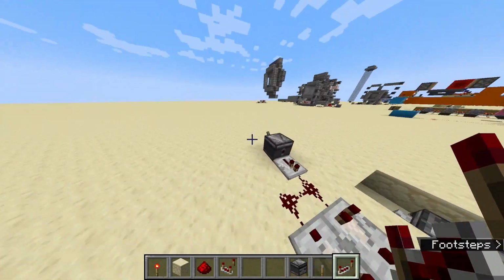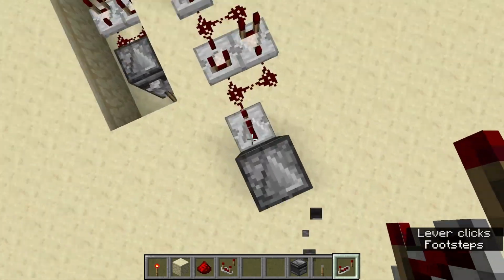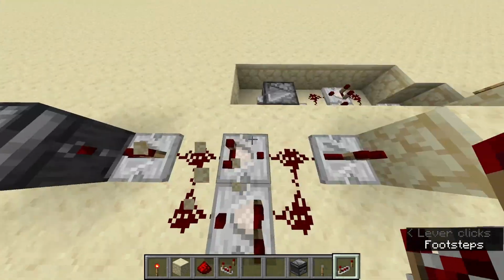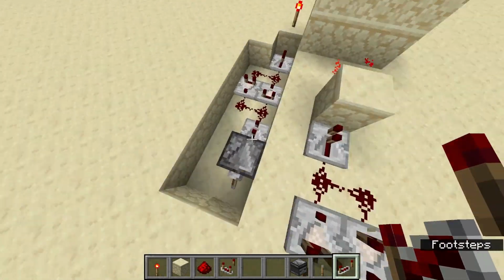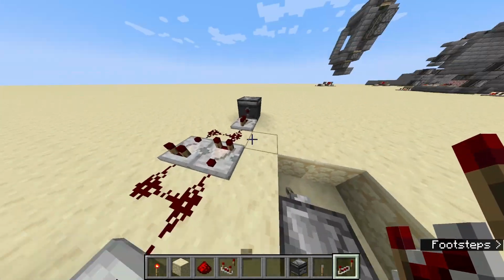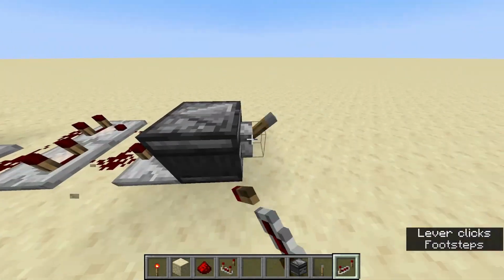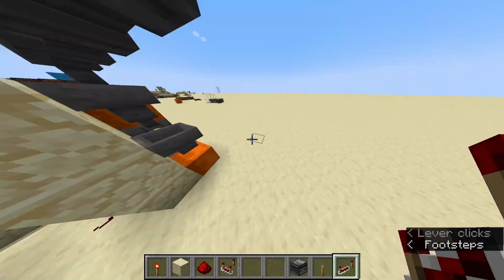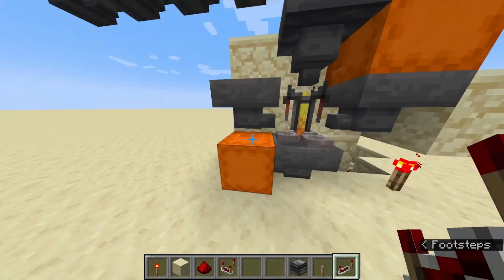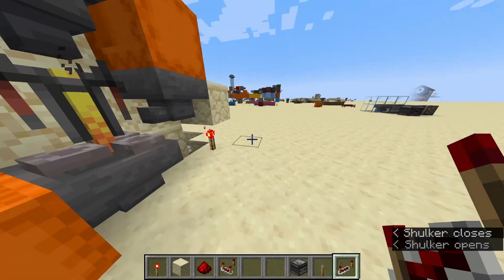So if I press this lever, which will run this dual edge monostable, which will run this pulse extender. Oh, I haven't set this to the right pulse length, that's what's wrong. So if I press that, was that enough to transfer all 3? Yep.